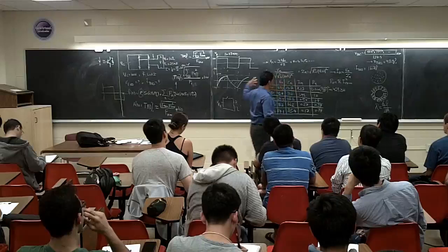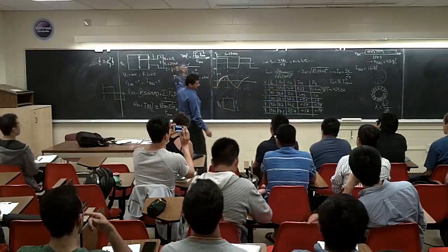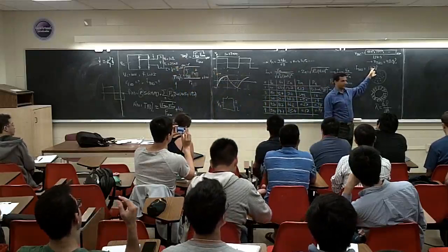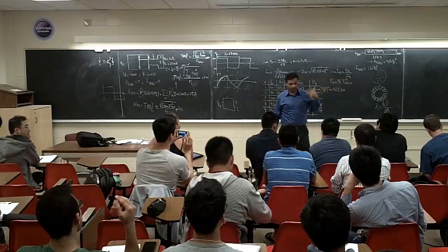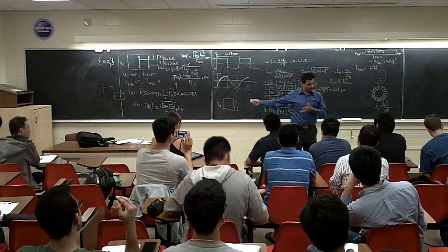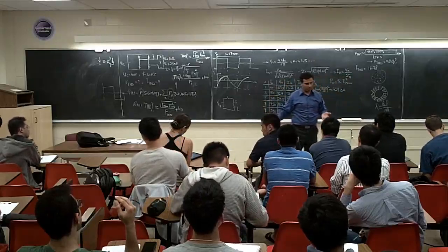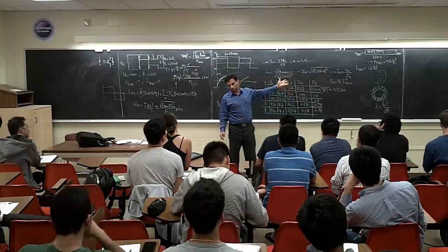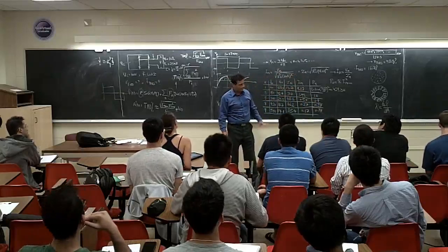Let's go solve the same problem we solved here. Make this one 50 milliamp. Just go to this one to see how much it's going to drop. I think this one is going to drop to 9%, something like that. Just double the inductor. See, this one is going to come down. But this is not the right way to do it because an inductor is also expensive, bulky, and heavy to add to the circuit. But I'm saying one way is to increase the inductor size in the circuit. It's going to help you reduce the harmonics in the current.